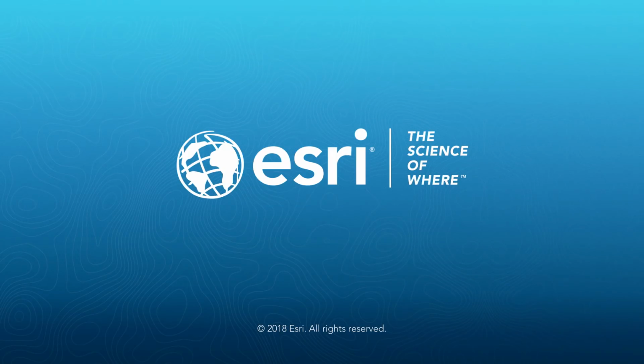Great questions. Licensing can be a tricky one. So by default, Pro is licensed using the named user license type. And with this license type, all Pro licenses are assigned by an ArcGIS Online or Enterprise Portal administrator. The same credentials you use to log in to that portal or ArcGIS Online organization would be used to log into Pro. Alternatively, you can also license Pro as a single use or concurrent use option, which requires a conversion in My Esri.